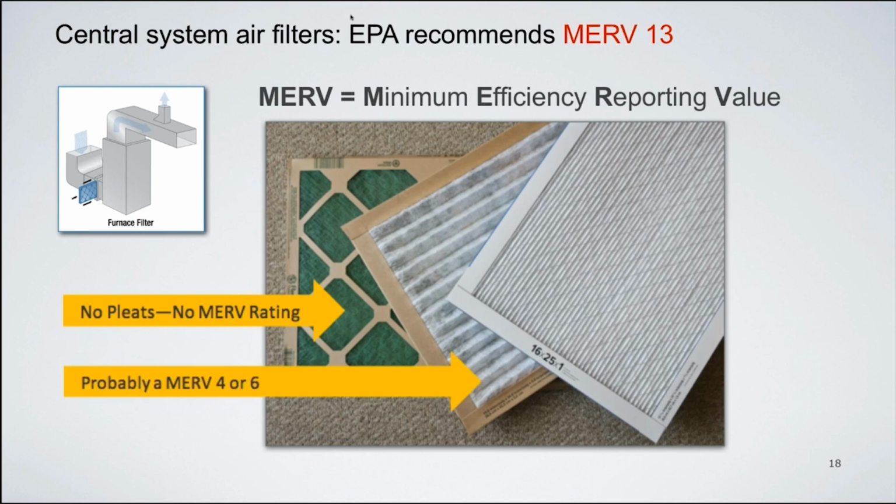The next level, which you can see there, is a white pleated filter with some fairly open, broad pleats, but that still means that there's more surface area available that the air can pass through, and the more surface area you have of the filtration media, the easier it's going to be to take out a larger number of particles, especially the small ones. So what this photo suggests is that that's maybe a MERV 4 or a MERV 6. In other words, it's going to take the larger particles out, some percentage of them, and that's certainly going to be an improvement over a non-MERV rated filter.